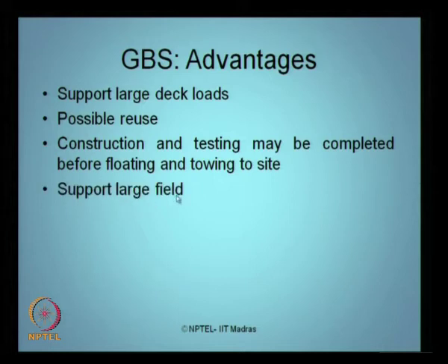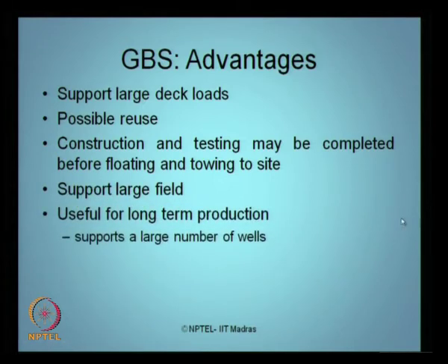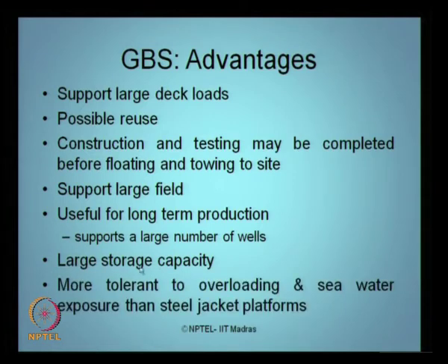They support large fields of oil exploration. They are essentially useful if you have a long term production. On the other hand, if you have a large number of wells which are yielding oil at a very high rate, then gravity based structures are a very good choice to support a large number of wells. One of the greatest advantages of this kind of structure is that they have a very large storage capacity. They are more tolerant to overloading and seawater exposure in comparison to steel jacket platforms, which we will see subsequently at the end of this lecture.